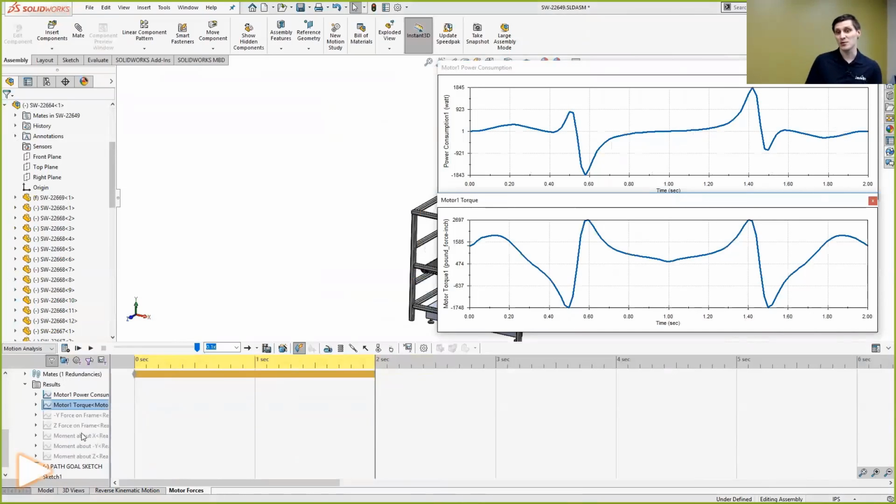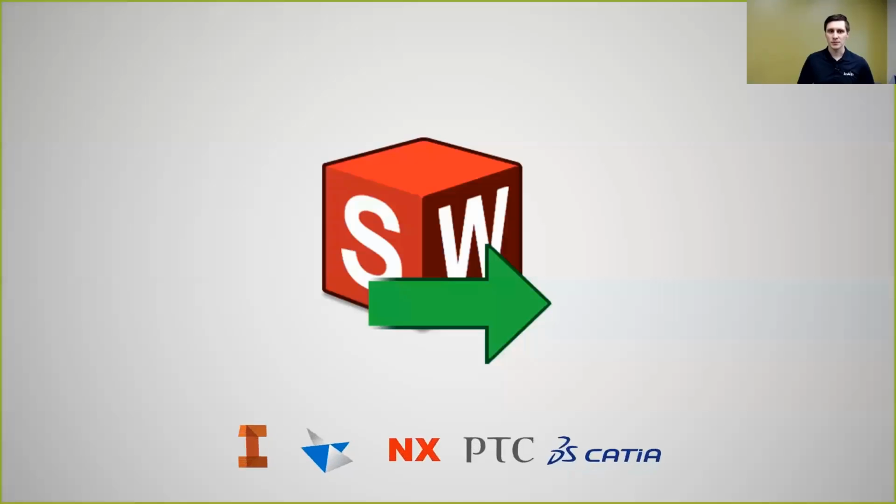In this case, some of the motors that we have spec'd out in this design, because this was an old design, maybe it was picking up something heavier, they're way over spec'd. So we're spending extra money on super powerful motors that we don't need. So we're going to find that out really early, and then that's going to let us save money down the road by re-speccing out different motors.